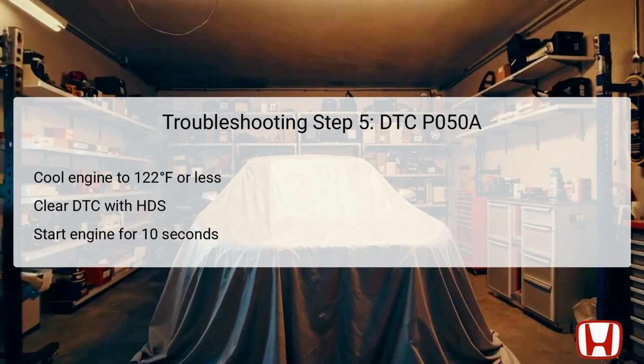that were previously logged. Following this, it's time to start the engine and let it idle for a minimum of 10 seconds to facilitate the re-evaluation of the idle air control system. Monitoring these steps carefully will enhance diagnostic accuracy as we continue through the troubleshooting process.